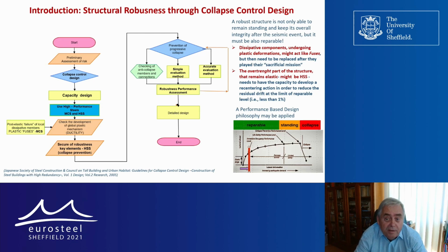And also we need to have overstrength components, which in principle are sized to remain elastic during the earthquake, which practically will maintain the structure standing up. A performance-based design philosophy can apply in order to have some criteria for a progressive development of damages during the earthquake.